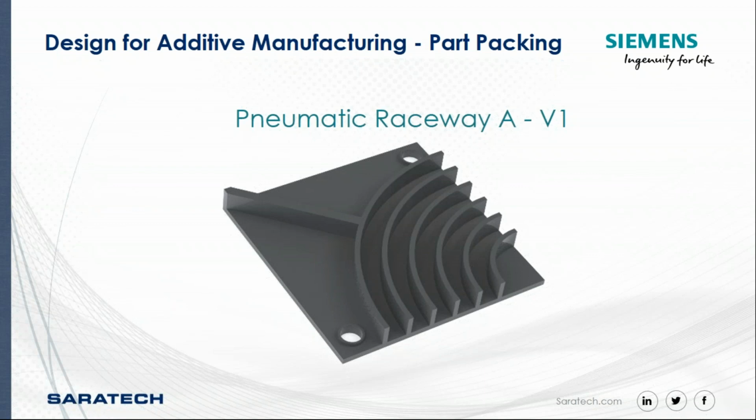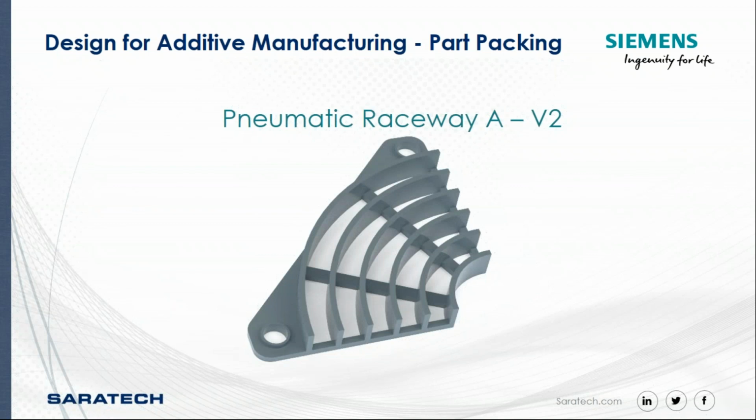So in this case, I've got this little plastic part. This came out of another assembly. I did not design this, but took it out of an assembly we had, and it's a little pneumatic raceway. There's 5 little tubes that go through these corners here, and it basically keeps the raceway from collapsing or kinking as the tubes go around this corner. So the first thing I did was I went through and redesigned this, and I basically stripped away a lot of the material that I didn't think was necessary to try and get a print that would be as efficient as possible for additive manufacturing.